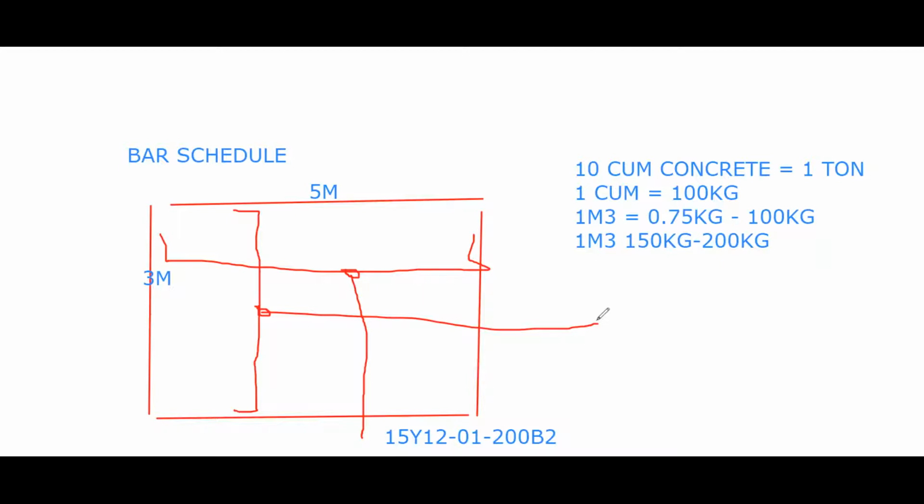The number of beams, what is the value for one beam? So it's a 450 by 230 beam. Most of them are 6 meters, end to end, based on the slab bay. As soon as I got it, I was able to get, let's say, 2,000 cubic meter of concrete for first floor, second floor, third floor, and that is it. And then for reinforcement, bam. For formwork area measurements, which we're going to do now, I came up with the bill.